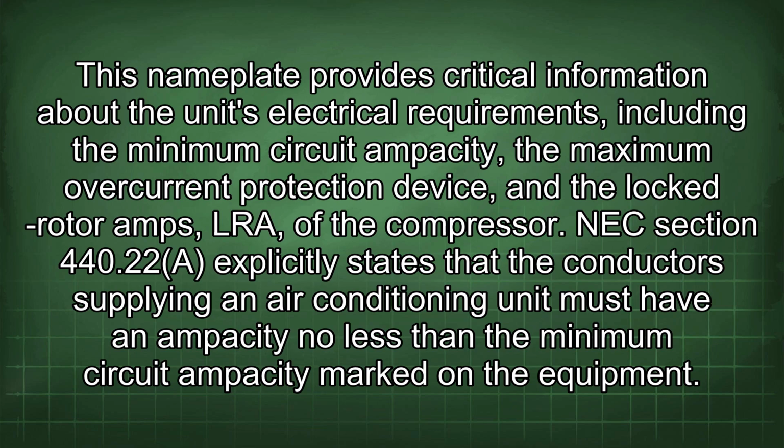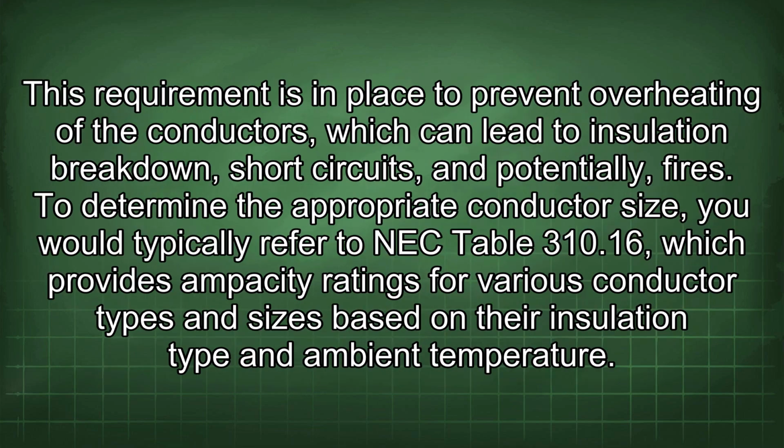This nameplate provides critical information about the unit's electrical requirements, including the minimum circuit ampacity, the maximum overcurrent protection device, and the locked rotor amps (LRA) of the compressor. NEC section 440.22 explicitly states that the conductors supplying an air conditioning unit must have an ampacity no less than the minimum circuit ampacity marked on the equipment. This requirement is in place to prevent overheating of the conductors, which can lead to insulation breakdown, short circuits, and